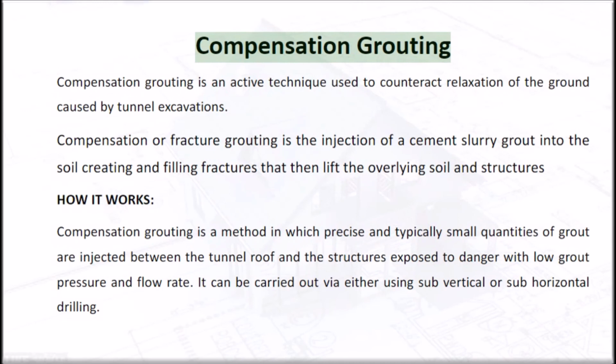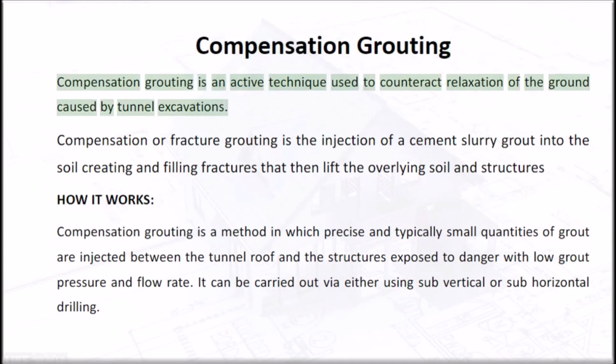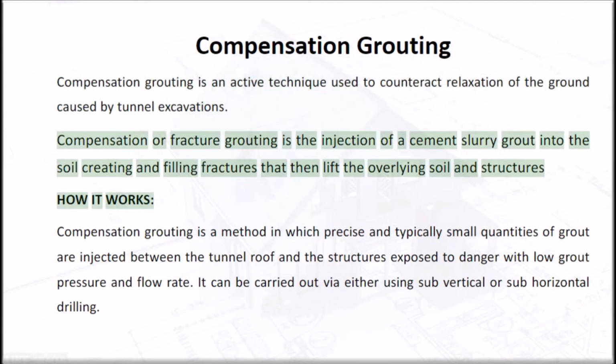Compensation grouting. Compensation grouting is an active technique used to counteract relaxation of the ground caused by tunnel excavations. Compensation or fracture grouting is the injection of a cement slurry grout into the soil, creating and filling fractures that then lift the overlying soil and structures.